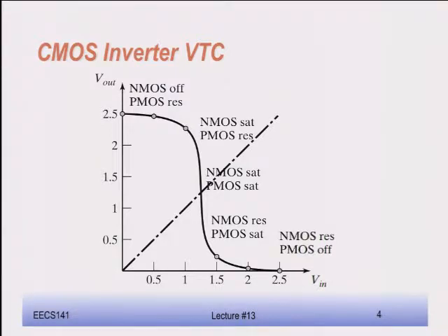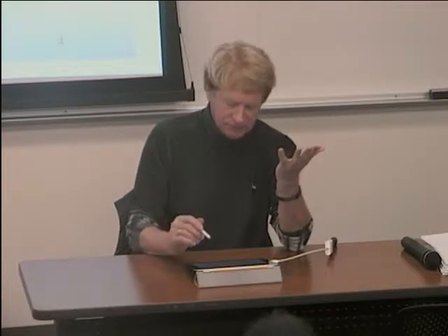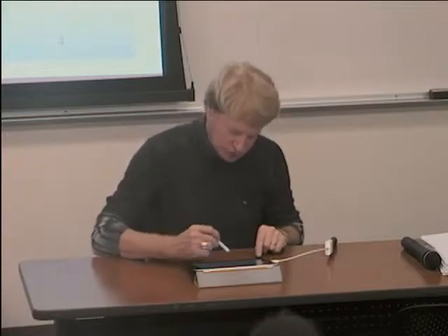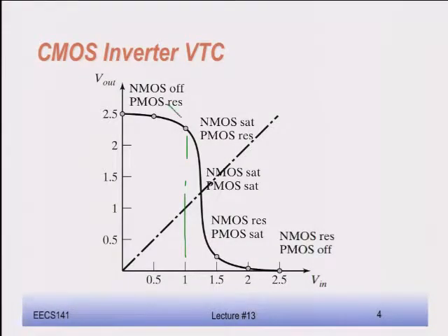You could look at the gate voltages where one of the transistors would turn on. Right. So, yeah, it's the same thing, right? Well, it's not really turn on. What's the definition of VIH and VIL? The slope equals -1. That's right. Slope -1. So let's look here at approximately this point here. I would say this is approximately -1 at 45-degree line.